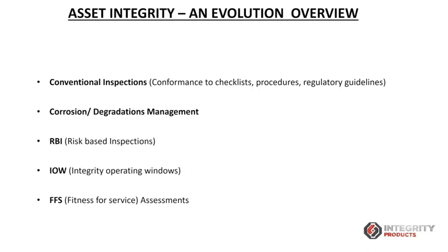And also, the main concept of IOW is that we have to operate the equipment or the vessel or any asset within the limits that are safe for the integrity of the vessel. So we do not exceed the safe operating limits of the vessel. So that is the concept of IOW. And then the last thing is the fitness for service assessment. We do the assessment of any asset using some analysis, some simulations, some detailed engineering calculations.